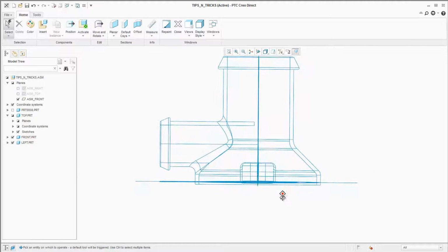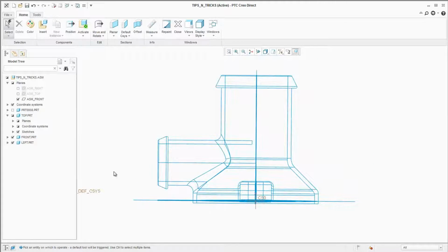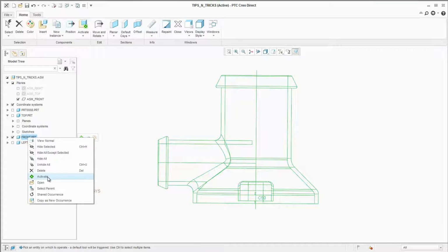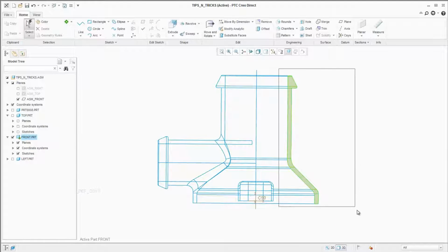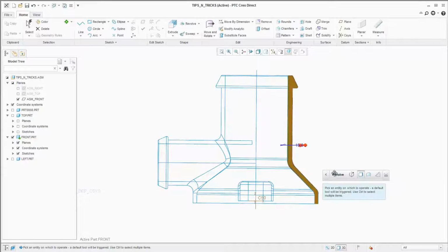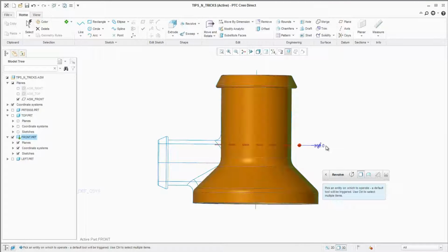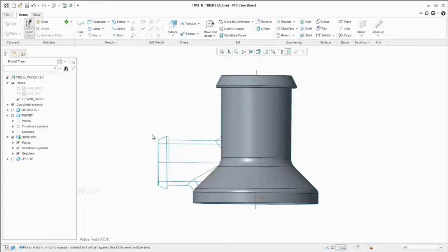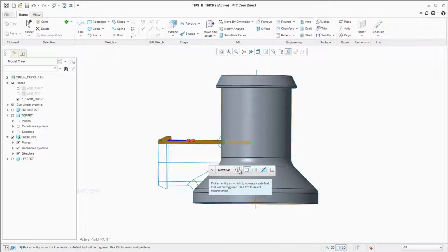It took us a bit to get fully prepared. As I said, this is a workaround still and not yet a fully tuned workflow. But from now on, things will roll. Let's create 3D geometry. As I do the box selection to define the input for my first revolve command, you see how the sketch regions are automatically being calculated and presented for selection. You can see that the creation of center lines that we did up front helps very much now as reference for the revolution axis.